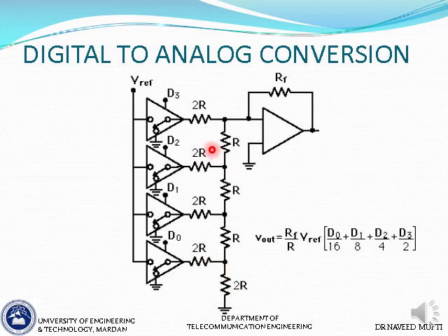And once again the principle is the same. It could be inverting, it could be non-inverting, it doesn't matter. Here our reference voltage is connected to every input, and every input is also connected to ground. So every feed to every resistor can either be connected to ground or connected to the reference voltage Vref, as you can see here. The switches are shown with the option of either connecting to Vref or connecting to ground.